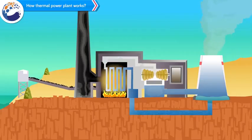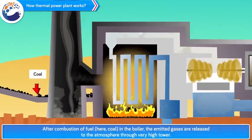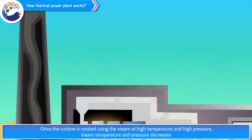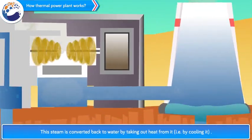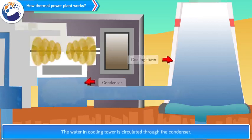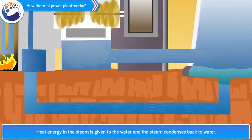How thermal power plant works. After combustion of fuel, in this case coal, in the boiler, the emitted gases are released to the atmosphere through a very high tower. Once the turbine is rotated using the steam at high temperature and high pressure, steam temperature and pressure decreases. This steam is converted back to water by taking out heat from it, that is, by cooling it. This is done in the condenser using water in the cooling tower. The water in cooling tower is circulated through the condenser. Heat energy in the steam is given to the water and the steam condenses back to water.